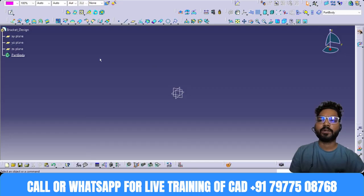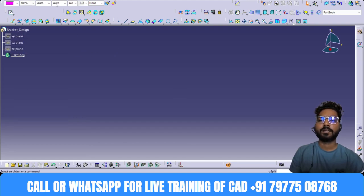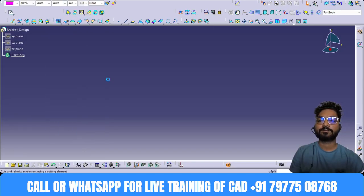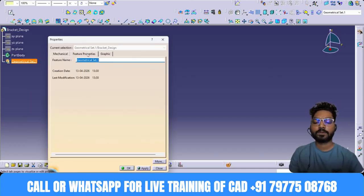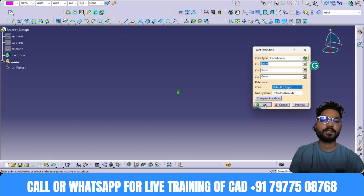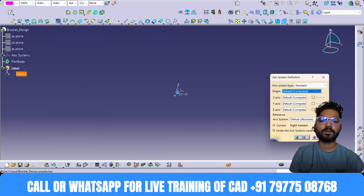So, first, what we are going to do: the default planes we will hide. You can right click and hide them selection after selection. Here we are going to insert one geometrical set. Add a geometrical set, and we'll rename it as input. Here we are going to create our input. For the input, we'll take one point at an XYZ coordinate value, and then we'll insert one axis system at this location. Click OK.